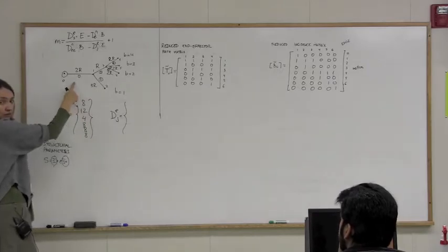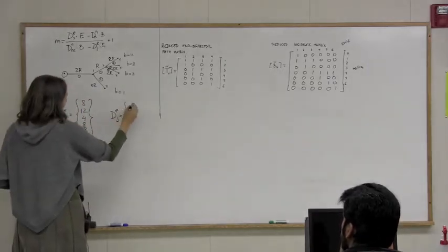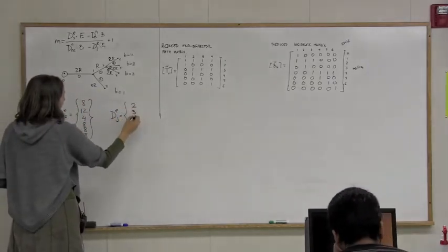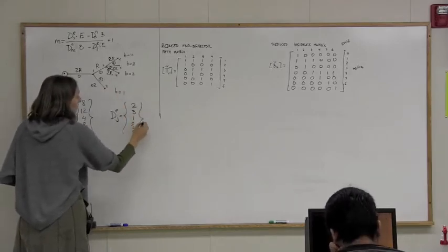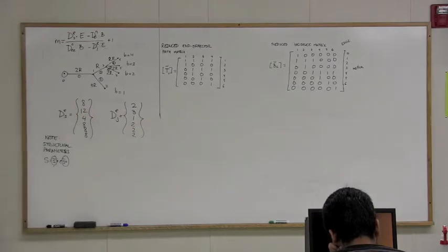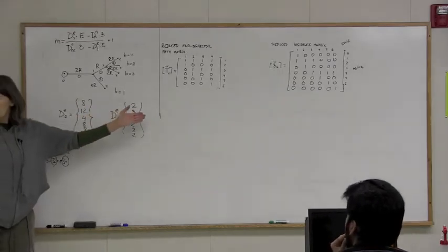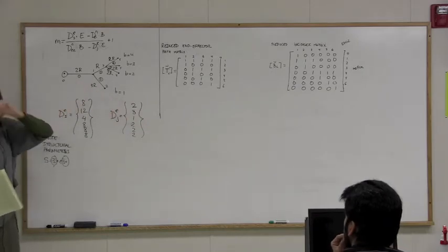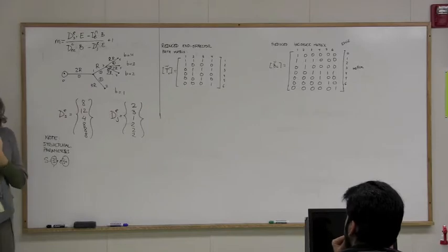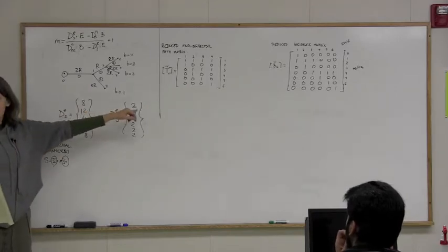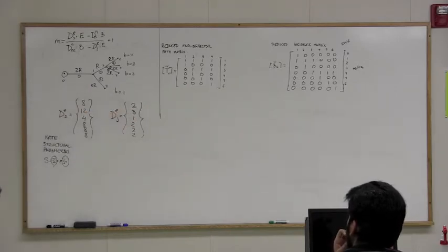2 revolute joints, 2, right? 3, 1, 2, 2, 2. If there is some relation between these joints, for instance if they are coupled, you can just put that there. Imagine these 2 revolute joints are coupled with a cable and they move with the same angle every time. Then you only have 1 independent variable, so you would put a 1 there instead of a 2.